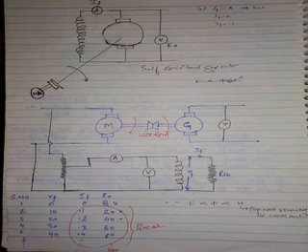Can you say that? This is one field resistance line. If you draw one more, this is one field resistance line which is increased. This is one more field resistance line for the field resistance which is critical. So draw a tangent to OCC. Let it meet at point R. Drop a perpendicular to meet at T.